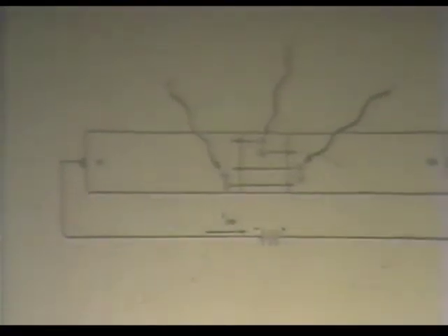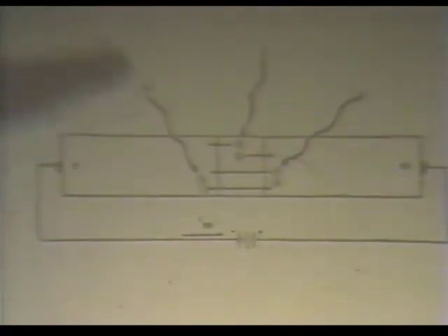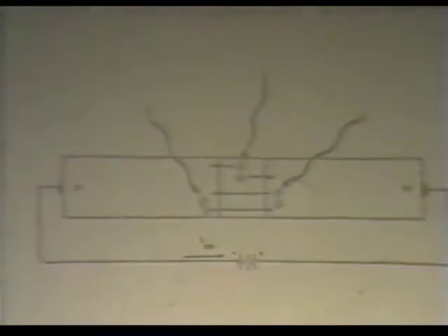Now, could the device be burned out because of that? The device could possibly be burned out, depending on how you've got it hooked in a circuit. Very rarely do you see a device destroy itself just sitting there. I won't say usually, you never have that, because somewhere you have stray capacitance or a bypass capacitor or something sitting there charged, and when you turn it on, it'll dump right through it also and could very well ruin the junction of your device.